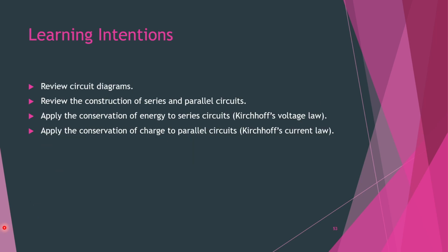So our key learning intentions today is to first review circuit diagrams as well as how we construct series and parallel circuits, and then begin to apply the conservation of energy as well as the conservation of charge to series circuits and parallel circuits respectively. When we look at the conservation of energy in series circuits, we begin to apply Kirchhoff's voltage law, and when we apply the conservation of charge to a parallel circuit, we apply Kirchhoff's current law.